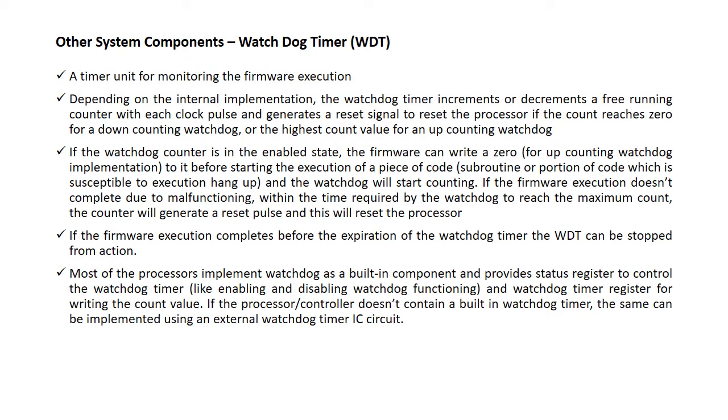Depending on the internal implementation, the watchdog timer increments or decrements a free running counter with each clock pulse and generates a reset signal to reset the processor if the count reaches 0 for a down counting watchdog, or the highest count value for an up counting watchdog.